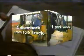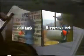In this case, the job can be divided into 8 individual steps. Park the vehicle at the fueling station. Disembark from the fork truck. Clear the fuel line. Disconnect the tank line. Remove the tank. Fill the tank. Reinstall the filled tank. Depart the fueling area.